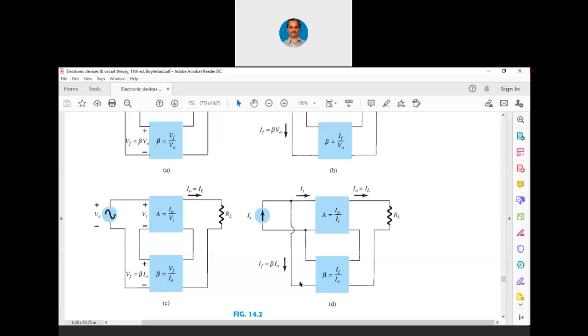Fine. The answer is, now this is negative feedback. It is not a positive feedback. In a negative feedback, we will purposefully supply the input in the opposite direction so that we reduce the gain, right? That is the answer. If it would have been positive feedback, then the current's direction would be upwards. But now this is a negative feedback. That is why later we will consider II plus IF equals IS. We always will have a phase shifting network in this feedback network also. That I have not yet told you.